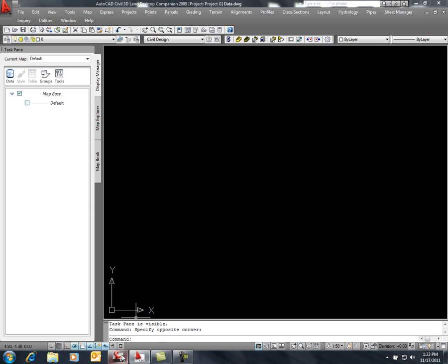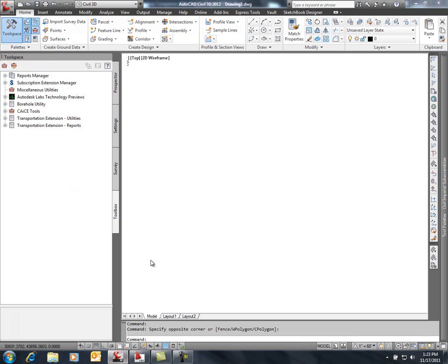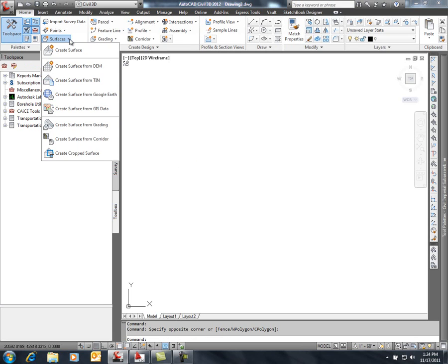So let's flip over to the Civil 3D side. And in Civil 3D, the first thing that I'm going to do is we'll bring in or construct our surface from the shapefile data. Now in many cases we'll receive shapefiles from customers, and it could be made from a number of different applications, but that shapefile will contain not only the geometry that makes up the contour but also the elevation, which is the important thing.